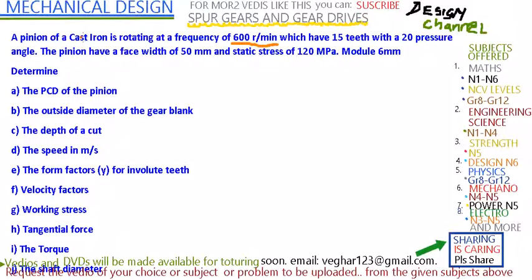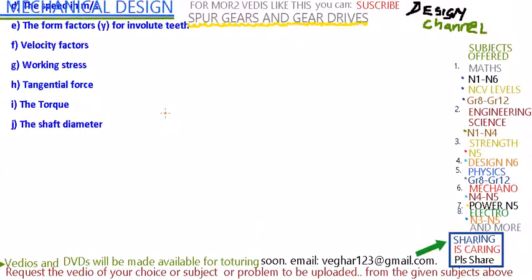A cast iron pinion is rotating at this frequency. It has this many teeth, then the pressure angle, the face width, and then the static stress. So they say calculate the PCD of the pinion. To calculate the PCD, part A, what does PCD stand for?